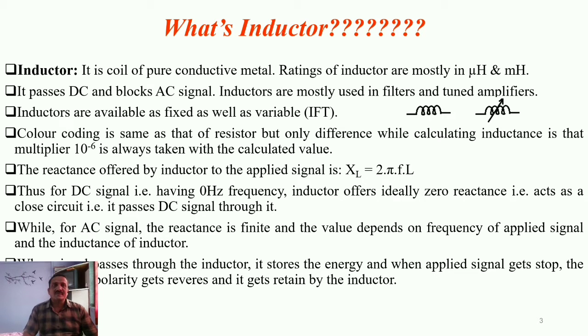The reactance offered by the inductor to the applied input signal is determined again by using a simple formula, that is XL equals 2 pi F L. So again, same as the capacitor, it is a frequency dependent component, right? By changing the applied signal frequency, the reactance of this component will change.